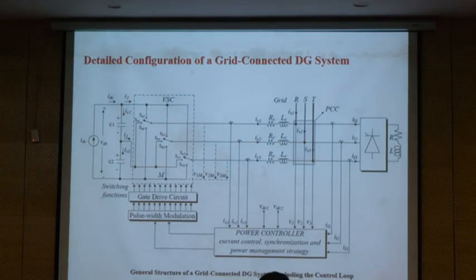So the stress over the transistor is less, or we can increase the power to 12,000. So it means that we can increase the power of the input and inject more power to the grid. So this is why we use the multi-level converter. Multi-level converter also has some other benefits like less THD and less harmonics, and also the filter is smaller, but probably that is out of scope.